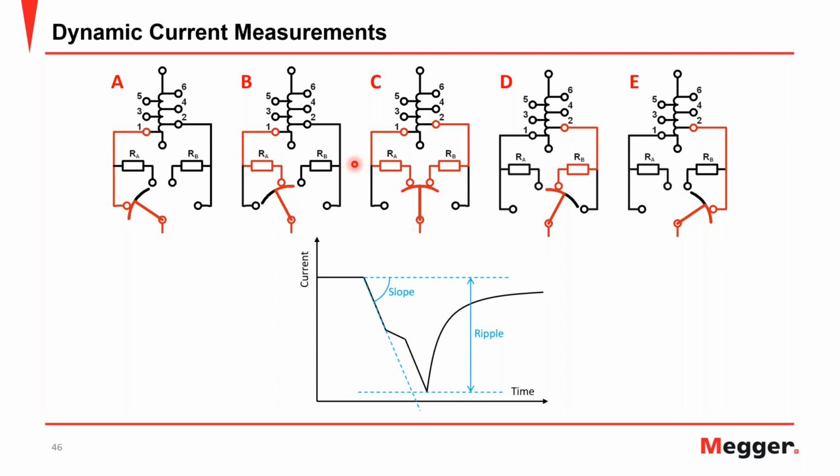Remember, the OLTC is designed to go from one position to the next without interrupting the flow of current. So these two are transition resistors, and you can see from these diagrams that you are actually adding resistance if you compare this position to position A, which is an actual position, like position 1. We said that as an example. So you are adding resistance to that path of current in that transition. So that's why your current goes down a little bit in that transition.